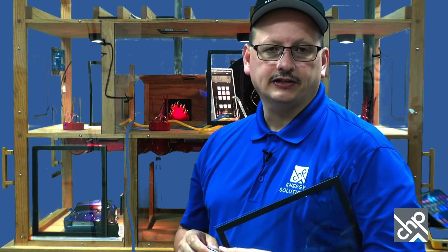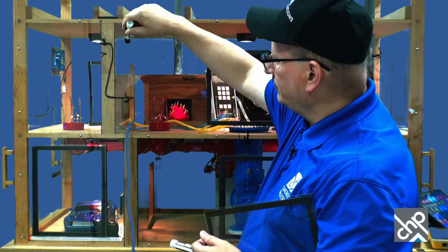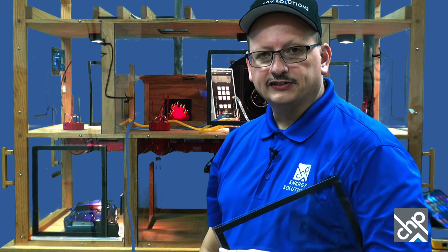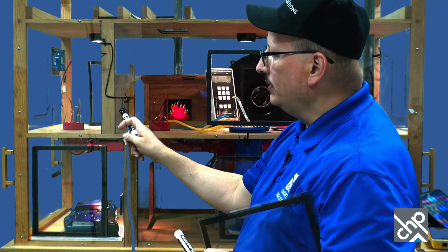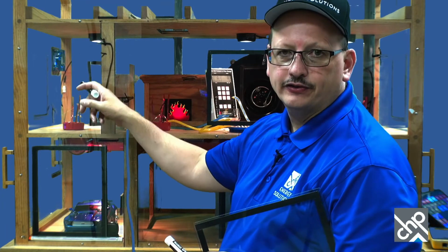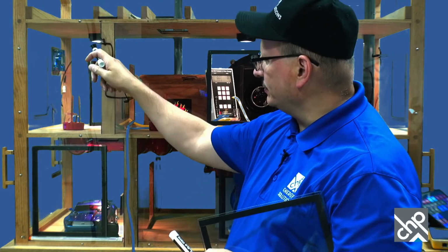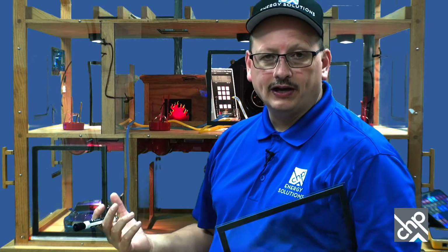Other ways to do it, like I say, you can go through the wall like I did here. And we don't put it directly through the wall because then you would get sound and light transfer maybe. So you kind of put it one high, one low. And usually you put it high in the bedroom because you might have furniture there, it'd be above. And obviously you don't want any bypasses in the attic or underneath, so you want the air to move through here. No plumbing in the wall, stuff like that. So that's one way to do it.